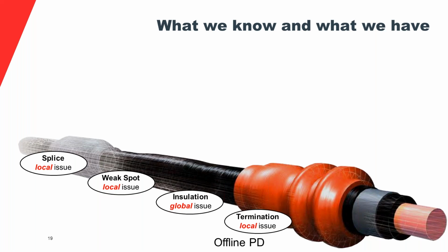It comes out of the cable manufacturer's plant, tested in a Faraday cage, up to 4 times operating voltage. With extruded cables, anything that is near 5 picocoulomb in terms of magnitude gets disqualified as a batch. So you should get these days a pristine cable out of the factory.